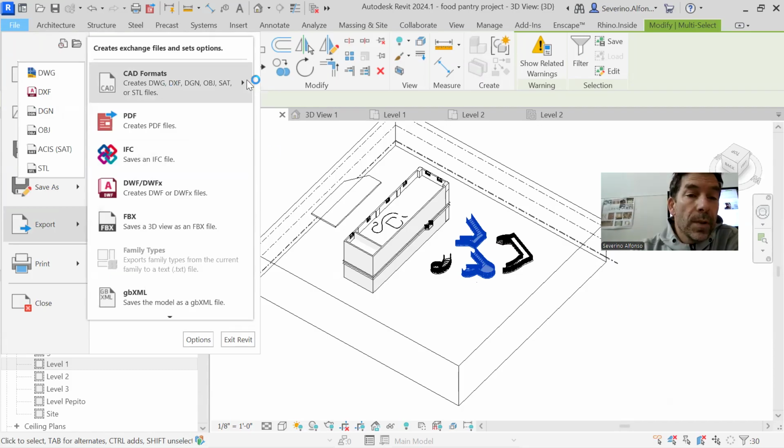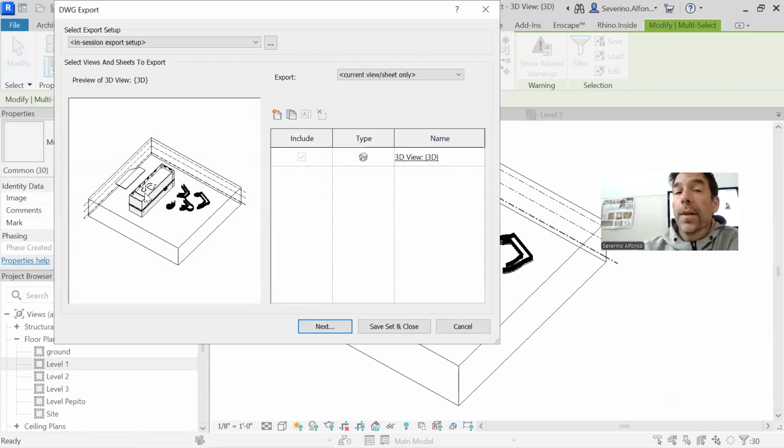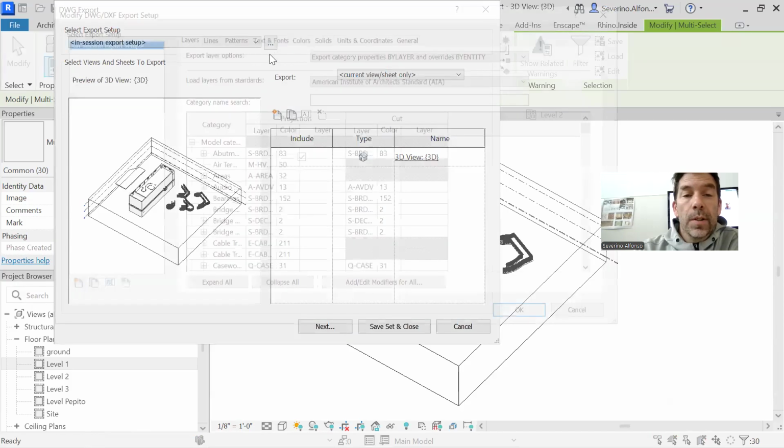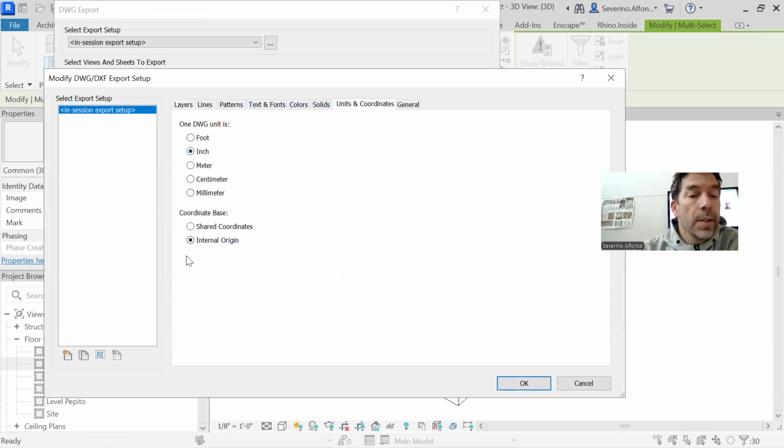Here it is, DWG. What you see in this window is the thing that you get later on. Now, before you send it, you can add more stuff later on, but one thing I would like you to take a look at is the list of layers that will come into Rhino, and AutoCAD, and Rhino therefore. One thing you should be careful about is units: we're working in inches. That's an important thing that you should share later on in Rhino. It's an inch world.